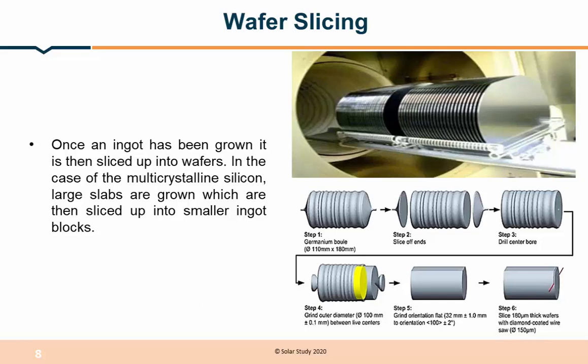After that the size will be 32 mm. Then in this final image it goes to the furnace, and using a high frequency laser, it slices these ingots into smaller wafers. That smaller plate is called a wafer, and its thickness is 180 micrometer.